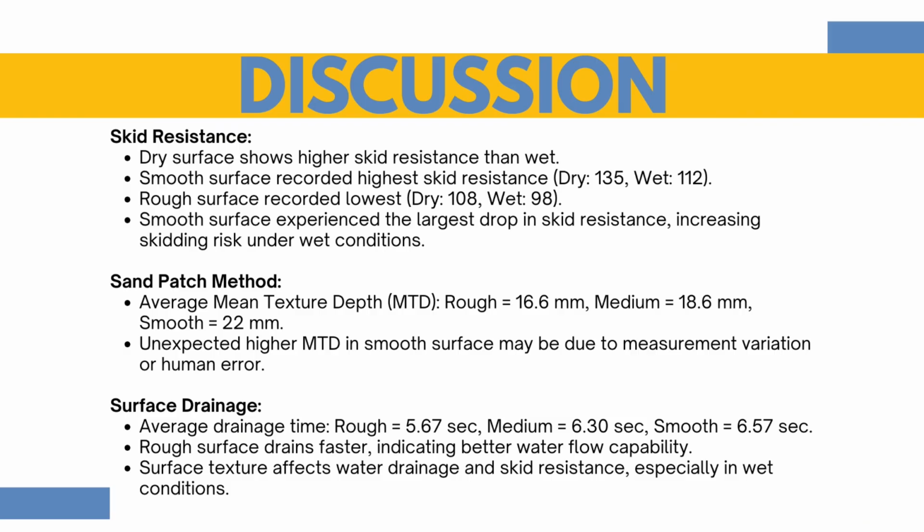Drainage times show the rough surface performed best, draining in just 5.67 seconds. Medium and smooth surfaces took longer, 6.3 and 6.57 seconds, respectively. This confirms that rough textures allow better water flow, which supports safer driving in wet conditions.